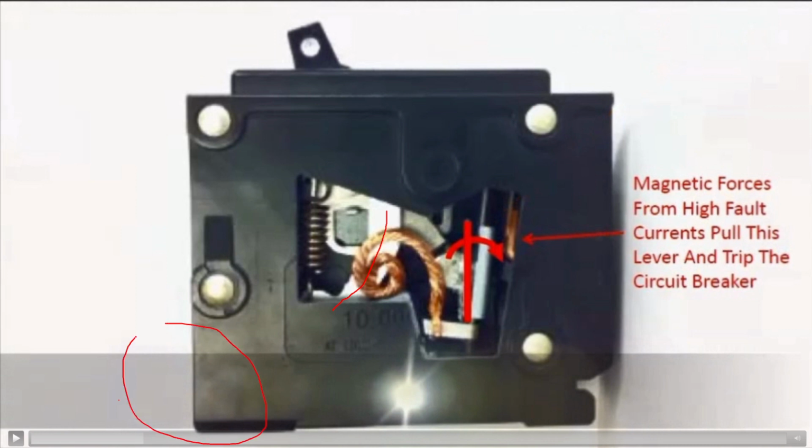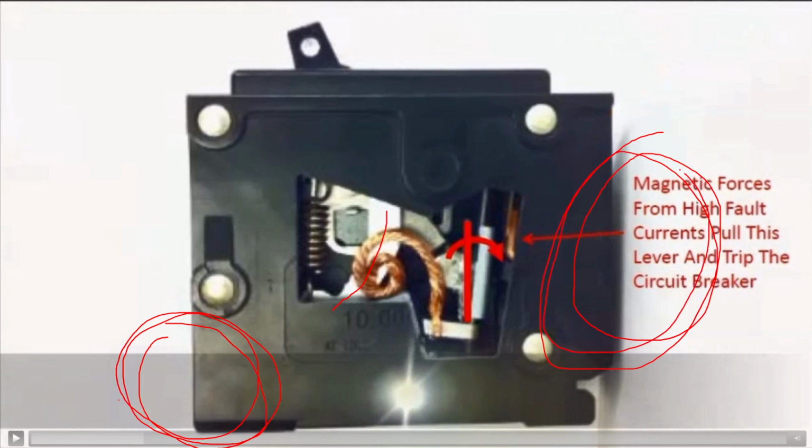this side here goes on the bus inside of the panelboard. Over on this side here is where we land our conductors going to the load. So the current is flowing from the source through this contact arm. Because of this braid, it flows this way, up and back down and out.